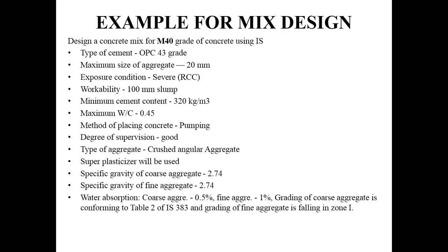In the question they have told us to use OPC 43 grade cement. They have assumed the maximum size of aggregate as 20 mm, and the exposure condition, that is the location where you are going to place it, is severe. Also, it is reinforced cement concrete. RCC means reinforced cement concrete, it is not plain cement concrete.